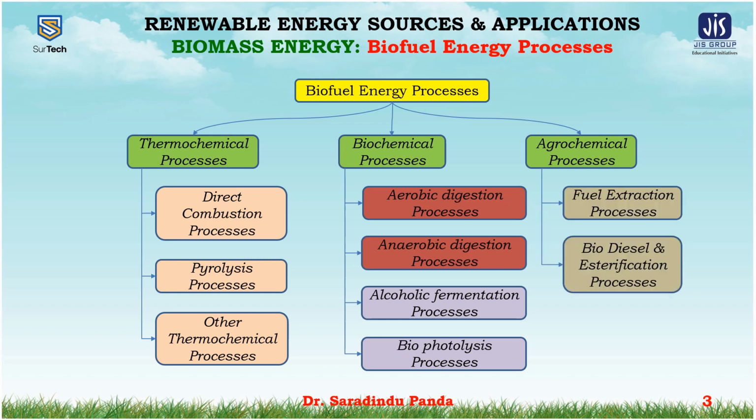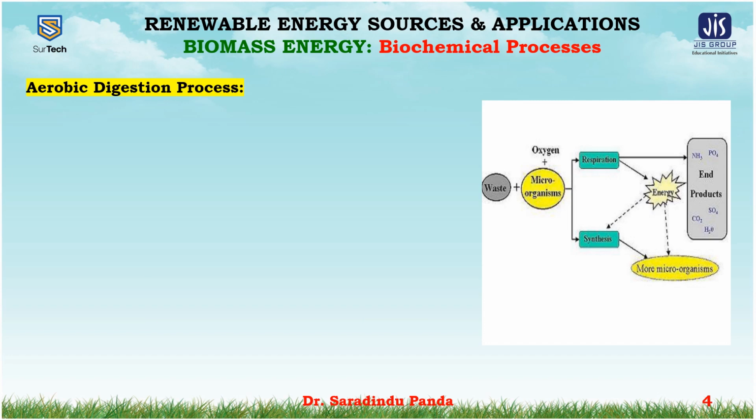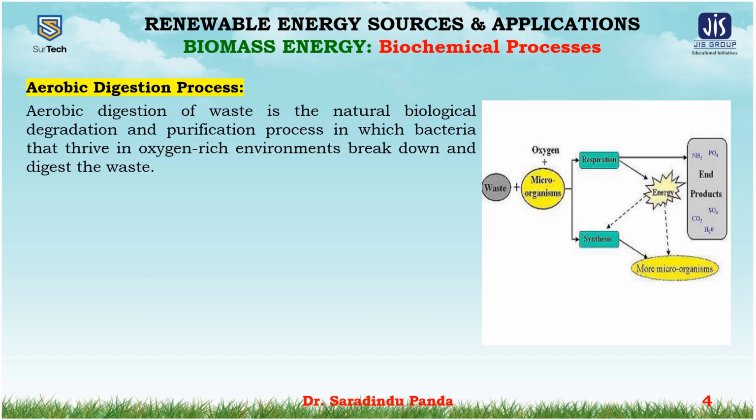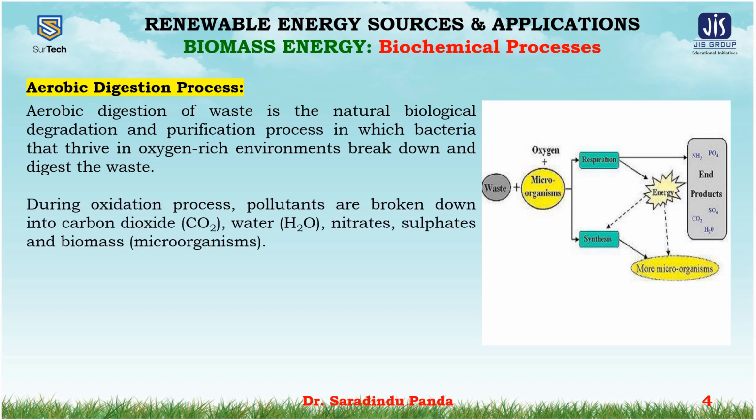The aerobic digestion process of waste is the natural biological degradation and purification process in which the bacteria that thrive in oxygen-rich environments break down and digest the waste. During the oxidation process, the pollutants are broken down into carbon dioxide, water, nitrates, sulfates, and biomass or microorganisms.